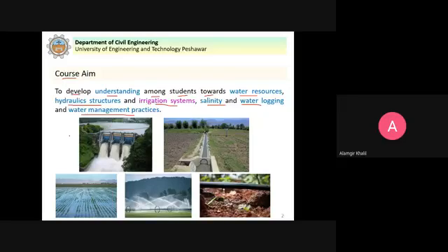If we had enough water flowing in the river and the discharge remained uniform throughout the year, then we wouldn't need to construct dams. We just regulate the river flow by constructing dams. When we have high flows in the river, we store that water, and during the low flows in the river, we release that water to meet the water demands.